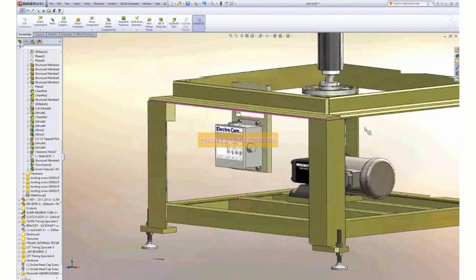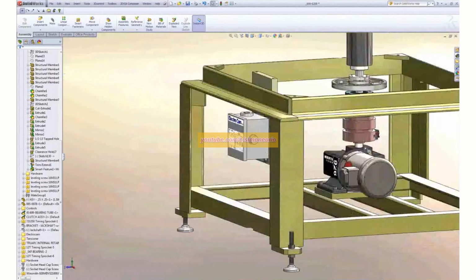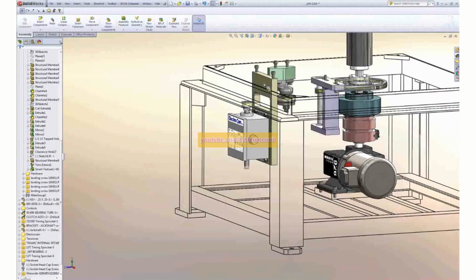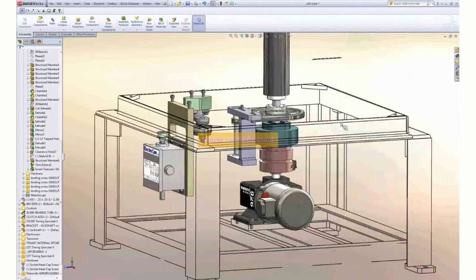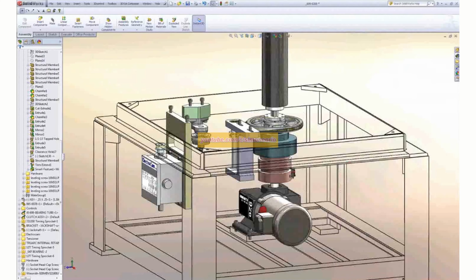But after we have that assembly pretty much finished, at least this section of the assembly, then what we would want to do is move up to our pulley system up here. So we need to make sure that the pulley is set and ready to go. So what I'm going to do is change my display style here. I'm going to go to my belt drive design. And you notice that, again, by changing the display states, it's showing me a couple different components out here, and it's turning transparent all the other components that we may not necessarily need.